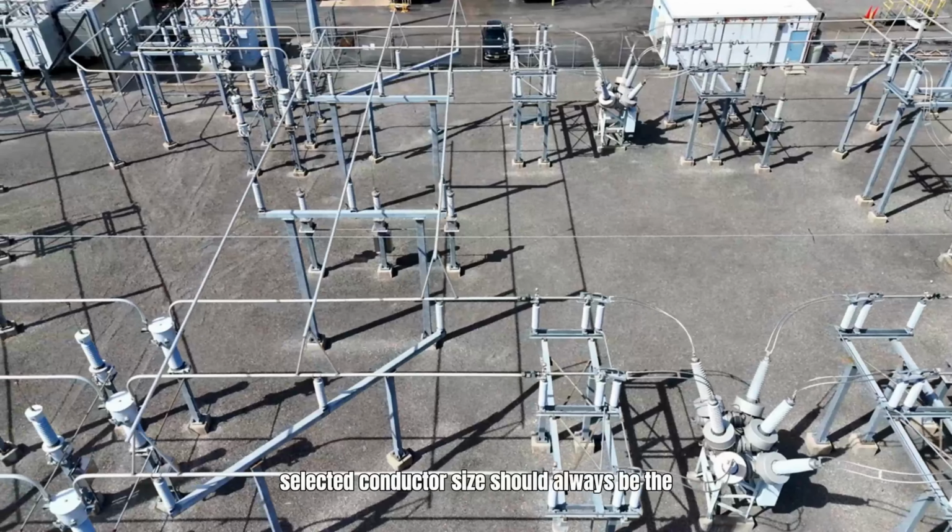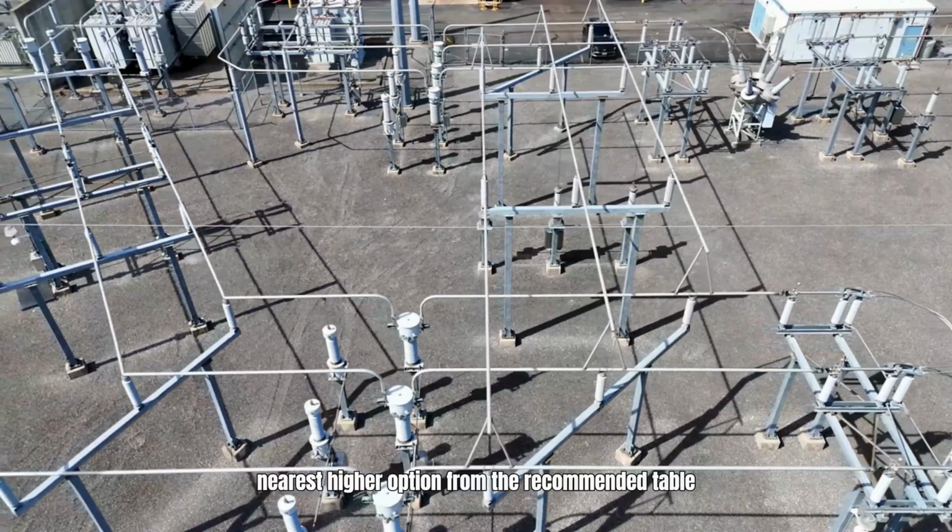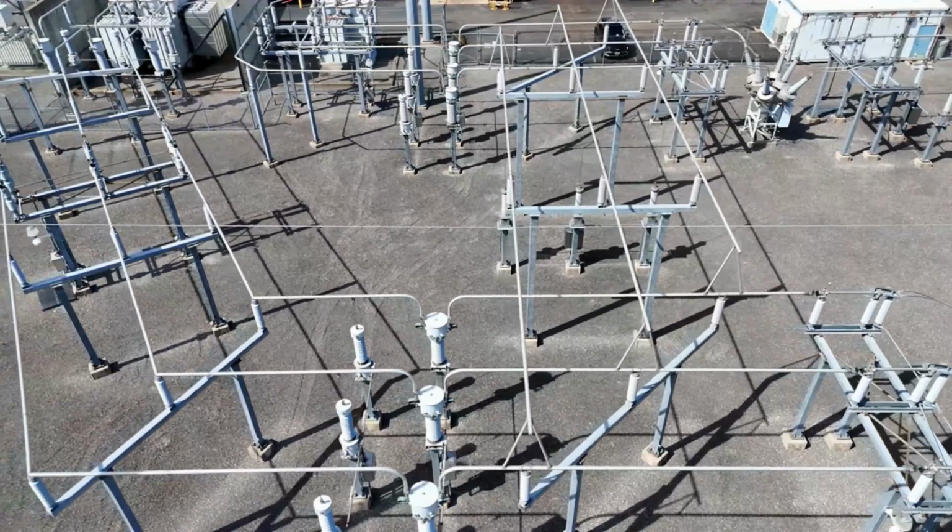The final selected conductor size should always be the nearest higher option from the recommended table to guarantee enhanced system reliability. This conservative approach ensures the conductor can reliably withstand intense thermal stresses from fault currents without ever exceeding its critical melting temperature limits. Ultimately, these rigorous and methodical calculations are absolutely vital for safeguarding personnel safety by maintaining touch and step voltages strictly below their tolerable safety limits.